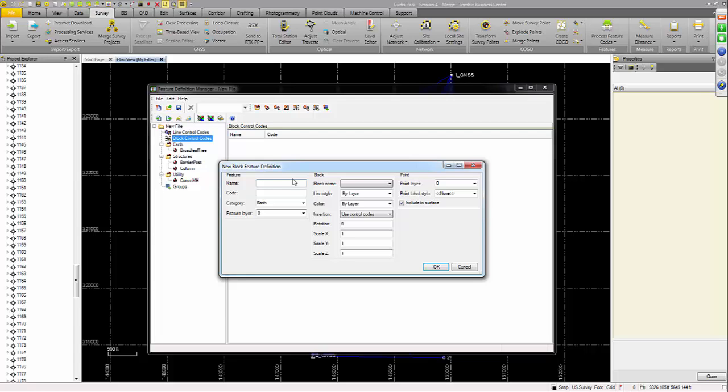And so you can define that block, pull it in, and then say, okay, I want to identify and I want to shoot in that block with 2 points, one on each diagonal corner. And so you can define that, say, okay, the first shot's going to be here, second shot's going to be here. That way it knows which way to rotate. It'll also scale that based on those points, and do the full transformation based on those 2 points you shoot.